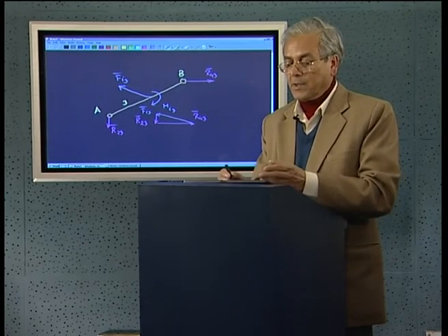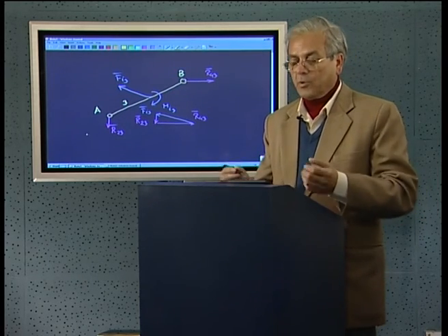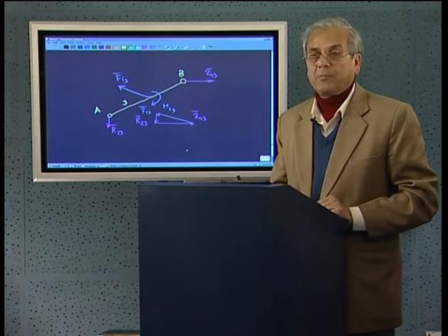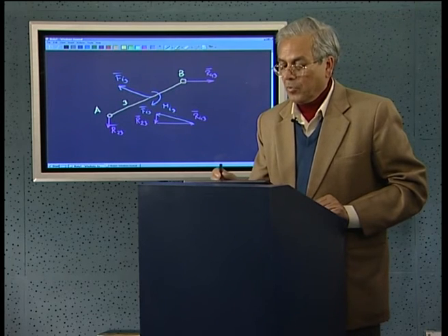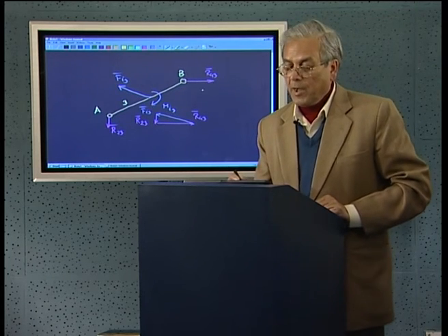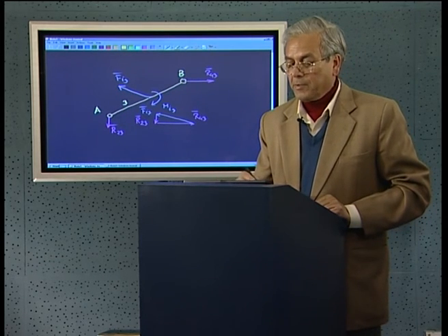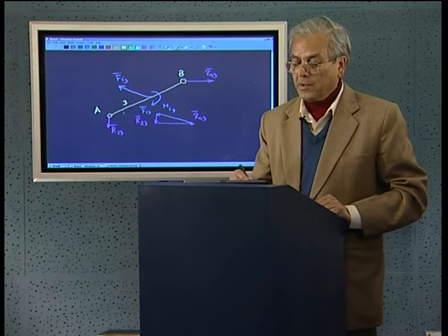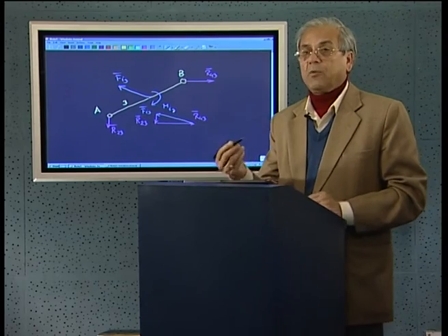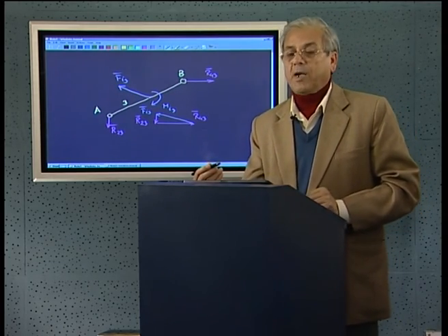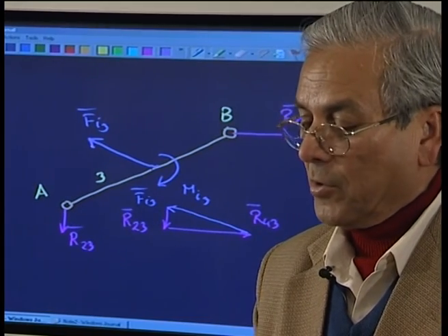Now, once that is known, we can go back to link 4, we can go to link 2 and find out the total force on those two links. It is quite possible, and once this force or loading is known, it will be possible for us to find out the bending moment, compressive force or tensile force on any section of any member, and if the material is known and the allowed stresses are given, it will be possible for us to determine the required cross sections, not to allow any failure because of this loading.